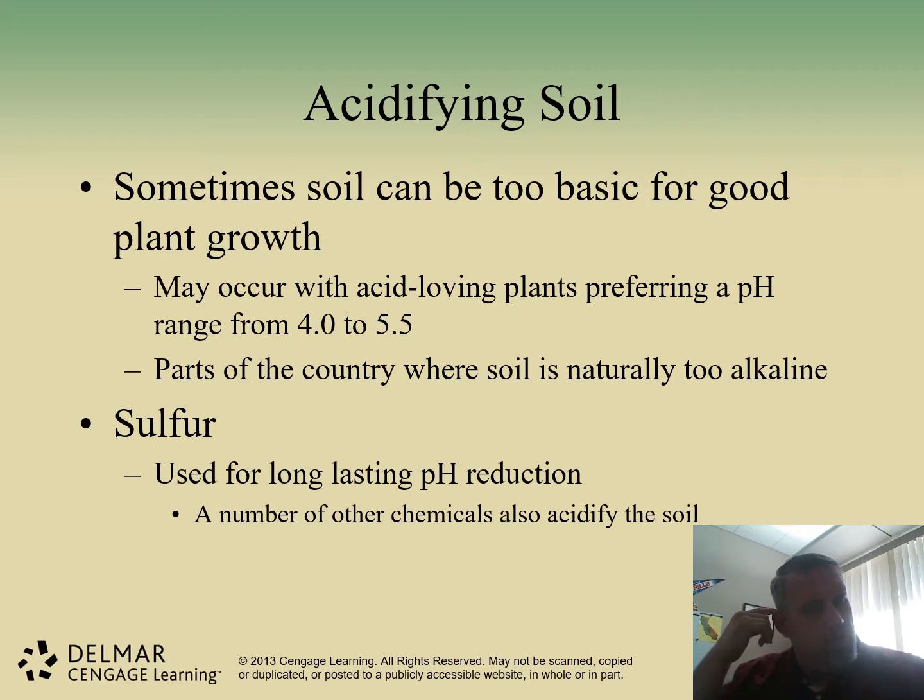So we'll talk a little bit more about this, and this is more up our alley. If you have a super alkaline soil, you want to use sulfur. That will create sulfuric acid once it's in the soil, and this can bring your soil down from 8.5 into your 7, your happy region. And this is what we do here in California.